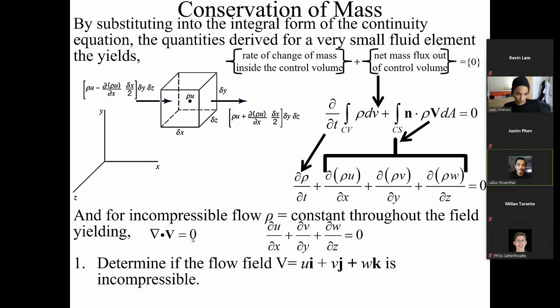Yes. So I guess I'm not as comfortable with that notation, the delta dot, right here. Yeah, just this one right here. So would that be the same as below, V would just equal 0? Yeah. So we would take each of these components, turn to partial, partial, partial, add them up, equals 0. Hey, we have incompressible flow. So that's how we can show that our flow field is incompressible.